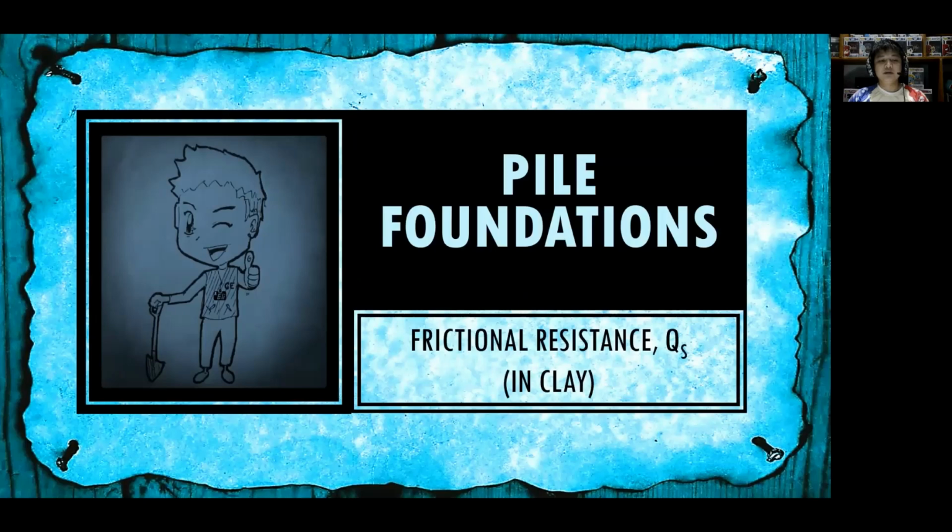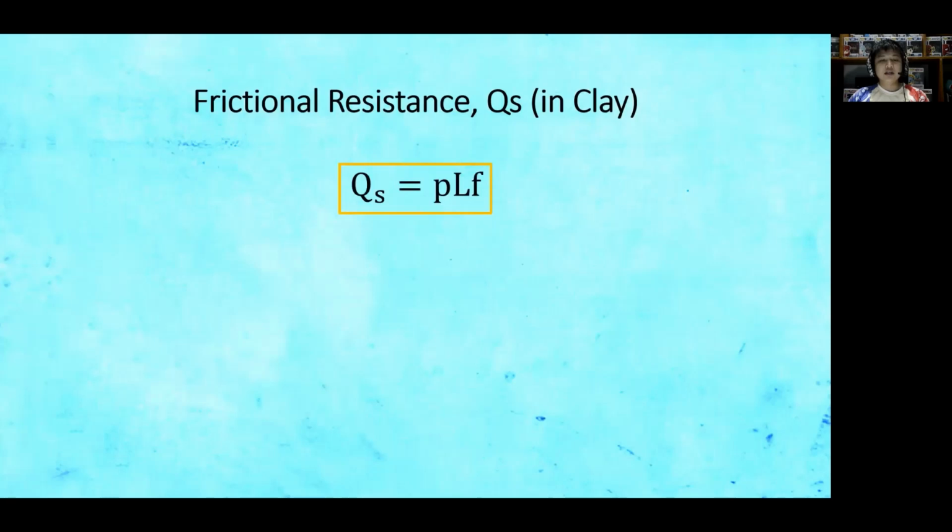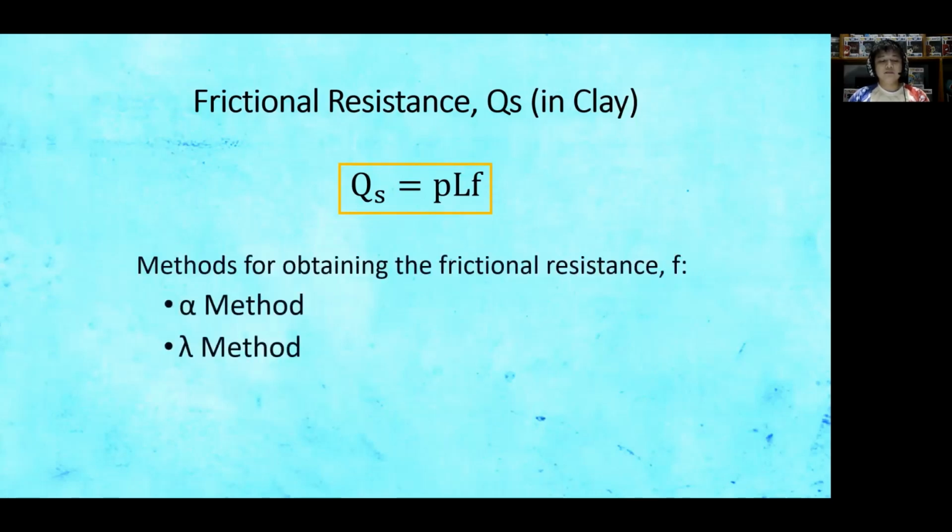Good day. The topic is frictional or skin resistance Q sub S for clayey soil. The resistance Q sub S is equal to perimeter P times length L times unit friction F. And the three methods are alpha, lambda, and beta method.